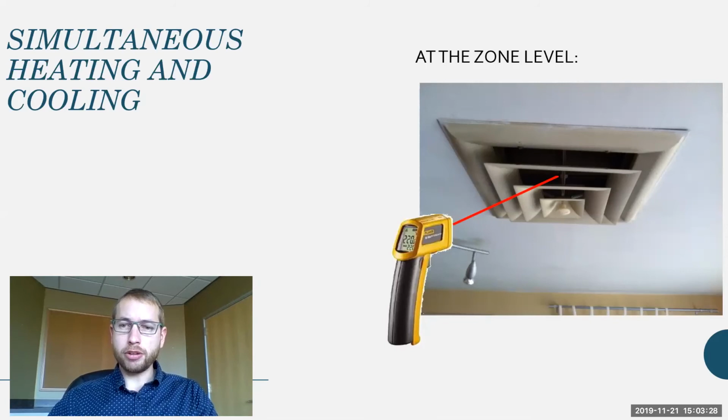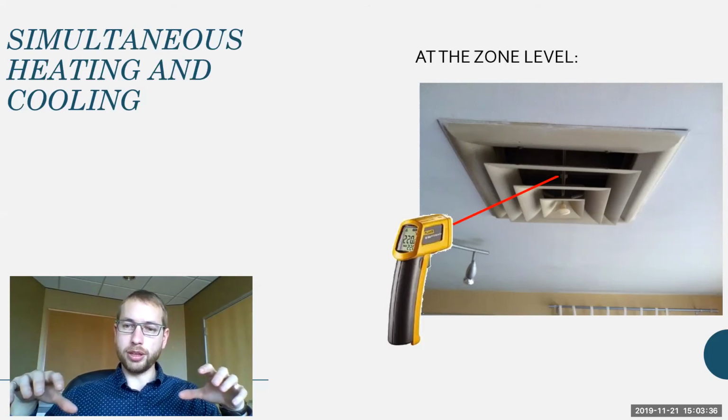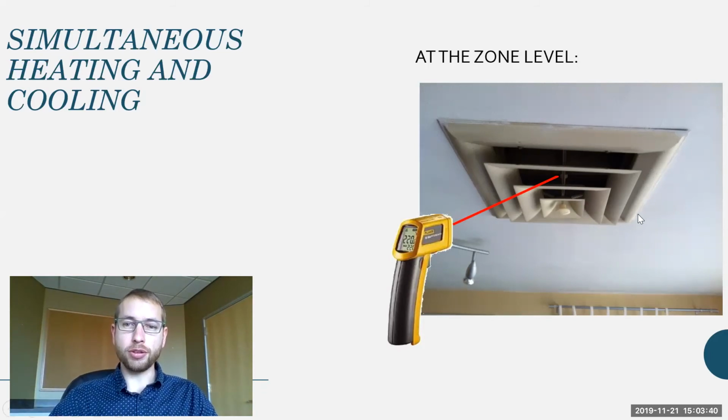When you're actually walking around inside the building, you can also have simultaneous heating and cooling within the same zone, or maybe it used to be two separate rooms within the office with a dividing wall that's since been taken down. And so you've got basically the battle of the thermostats, where the diffuser on one side is supplying hot air and the diffuser on the other side is supplying cool air, and the two of them are fighting. Not ideal for saving energy.